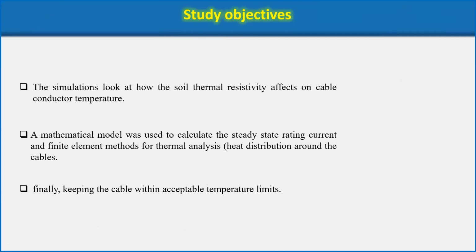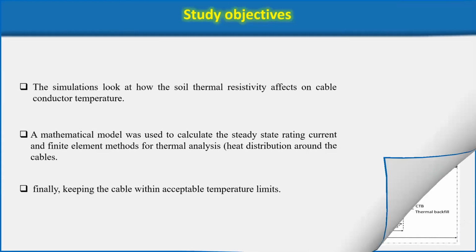talk about the simulation. Look at how the soil resistivity affects the cable conductor temperature. A mathematical model was used to calculate the steady state rating current, and the finite element method for the thermal analysis, heat distribution around the cable. Finally, keeping the cable within acceptable temperature limits.